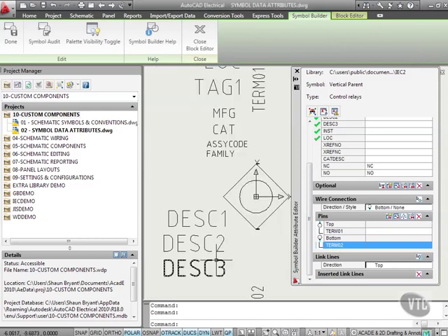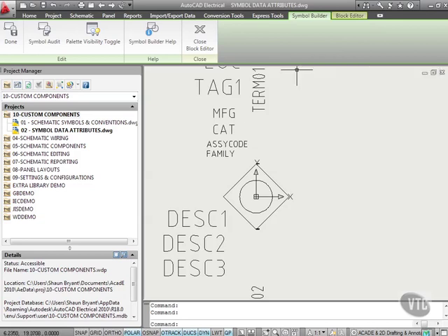So what I've done there, can you see, it's given me loads of space there, can you see that? So when these terminals appear on the drawing, they're actually justified. So terminal 01 justified to the left, terminal 02 justified to the right. So you can see there, look, terminal 02 to the right, terminal 01 to the left, if you were looking at that horizontally. So we've done that with the justifications of the pins in our terminals. So we are now pretty much done. So we need to close the properties palette, like so. So I'm going to close the properties palette, like that.